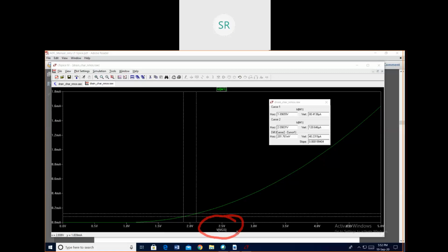Similarly, for drain characteristics also, you can give the label for the x-axis. So this completes the drain characteristics and transfer characteristics of the N MOSFET. Here there is no design actually, so you only have to rig up the circuit, change the edit simulation settings, and plot drain characteristics and transfer characteristics, and by varying some parameters you can see what the effect is on the drain as well as the transfer characteristics.